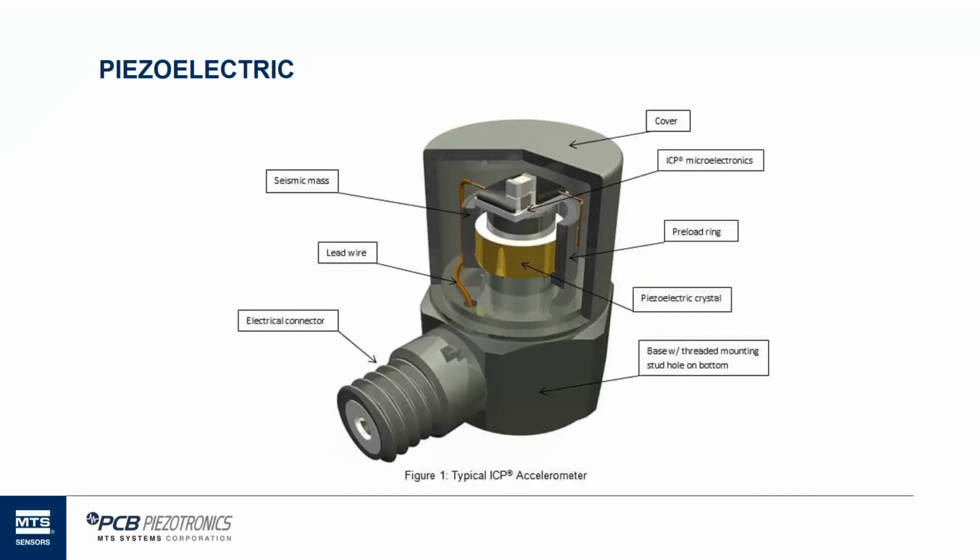And then immediately outside of that, we bond a preload ring. The preload ring is outside of the seismic mass. So you have 3 layers. We'll talk about 4 layers. The first layer is the mechanical ground. That's the post of this accelerometer that you see in the middle.